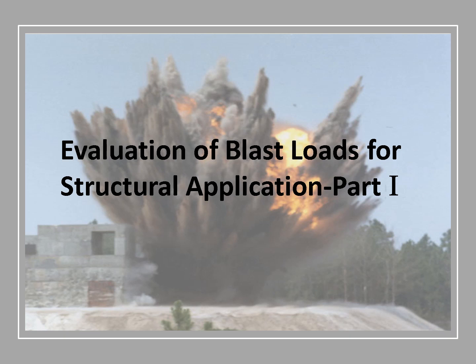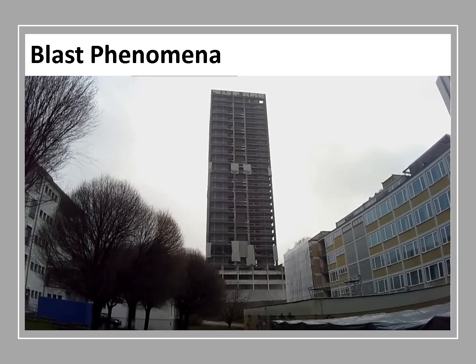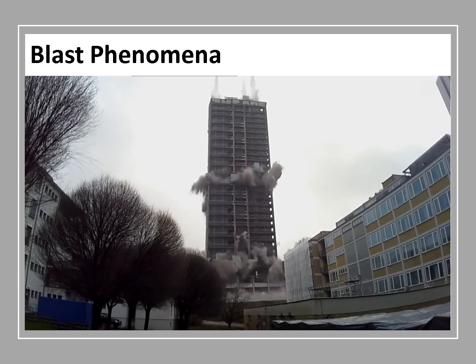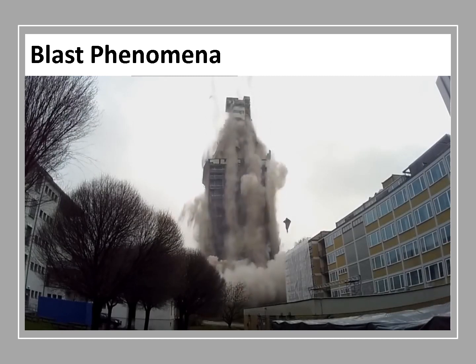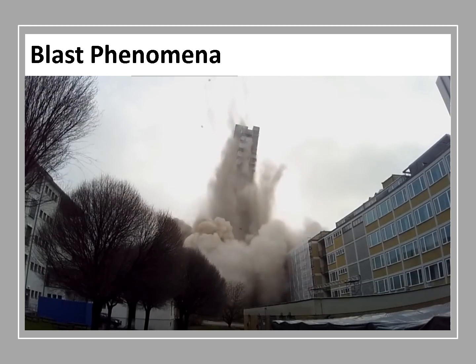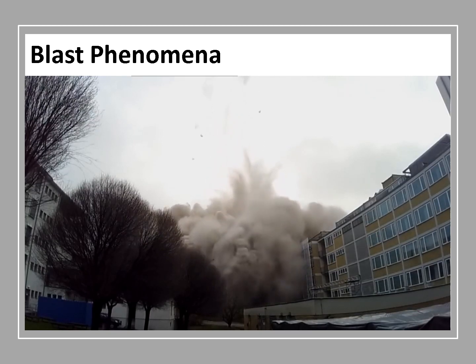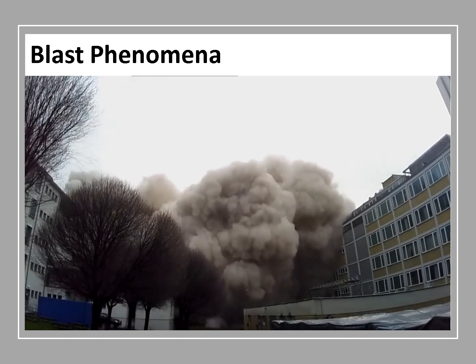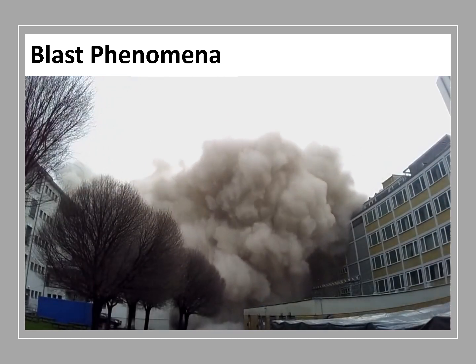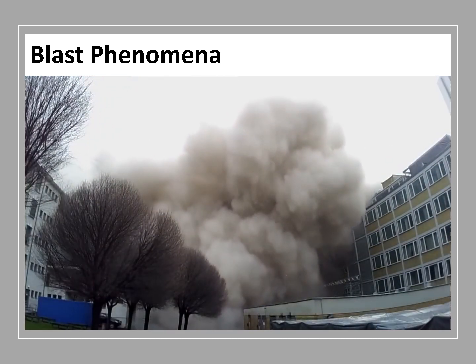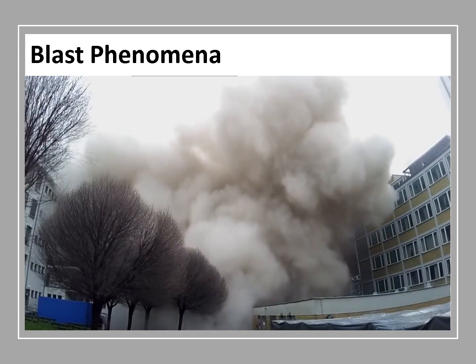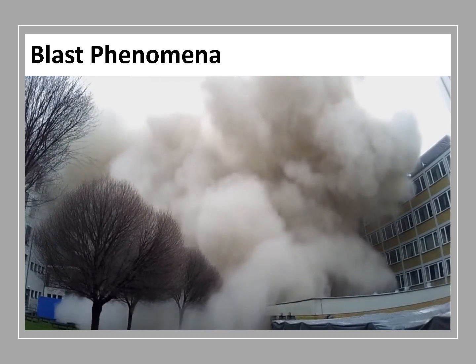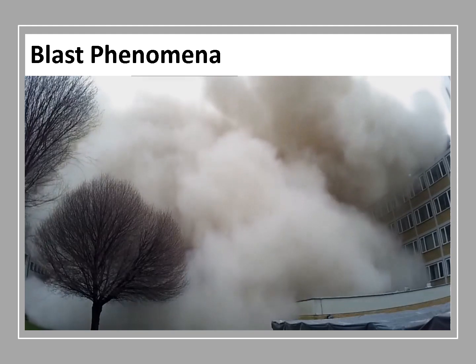Let's start with the blast phenomena. An explosion is an extremely brief chemical reaction that produces hot gases and lasts barely a few milliseconds. A blast wave will occur when these gases expand tremendously, compressing the surrounding air. The blast travels due to the disequilibrium between the compressed air forming the blast and the undisturbed air in front of it.